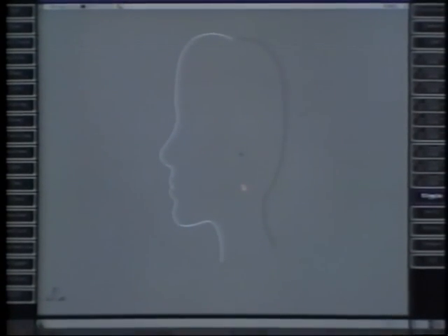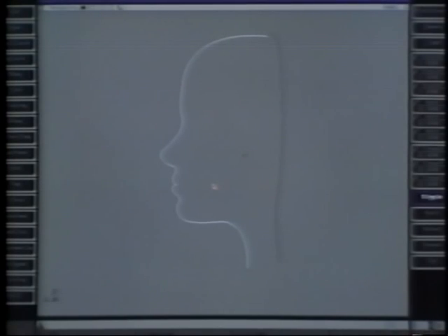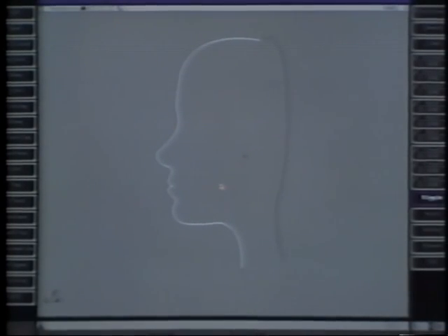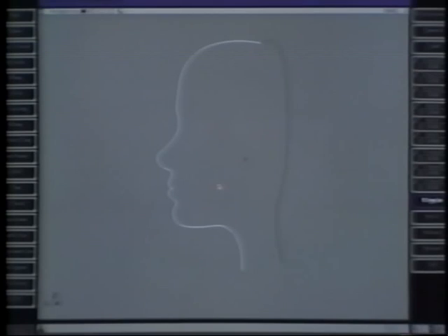For a human head, often the most important curve is the profile, which defines many of the key proportions. Then your second curve can be an edge defining the sides of the head. Don't make this too big, since you're modeling just the head itself without hair yet. Good visual reference is very important in getting these curves right. Next, we need to fill in the space between these curves. With our radial cross sections, we'll be able to skin together.